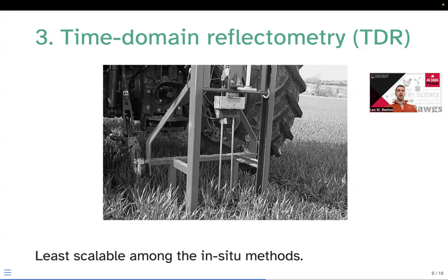In any case, this is something I've used for research purposes before, where you have a handheld TDR equipment that you take to a part of the field and insert. It also has these two rods, maybe not as deep as the ones we're seeing here, that you push into the soil and take a measurement. Potentially that equipment also has a GPS with it, so it takes a measurement and a position, and then you just keep moving through the field.